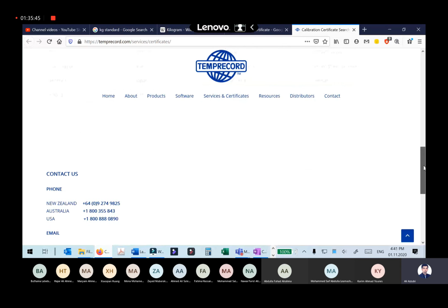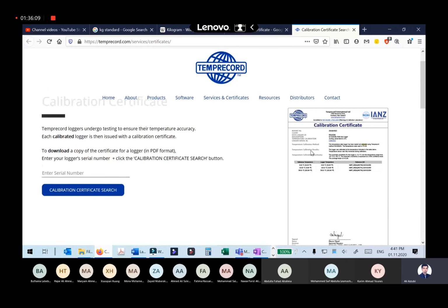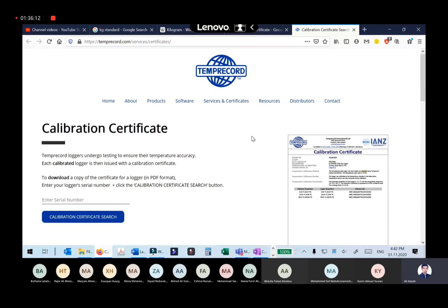your study. Okay, some sensors in the market, especially cheap sensors, don't provide this calibration certificate, and sometimes it is more expensive than the sensor itself. The certificate can be more expensive simply because you need a reference, which is expensive. You need accurate data, lab research, so the calibration can be really expensive. So whenever you do studies, research, and you need something trustworthy, and you need to be confident about your readings, you need to consider such calibration certificates.